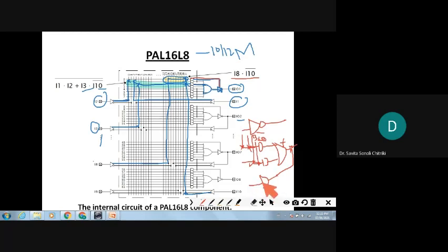What is it that he is telling? I8, you should get I8, and the one more thing is I10 bar. That means it is not only the inverted output, but also it is tri-state. It has to be enabled by this condition. All of you are getting this?